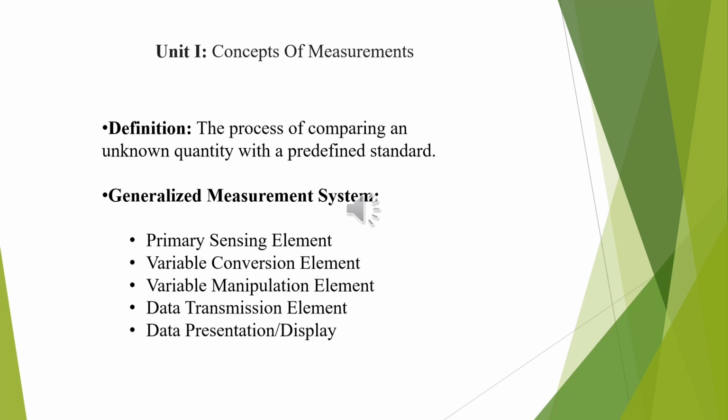Syllabus overview. First lesson, we are going to focus on the concept of measurements and the generalized measurement systems. The generalized measurement systems are primary sensing element, variable conversion element, variable manipulation element, data transmission element, data presentation elements.